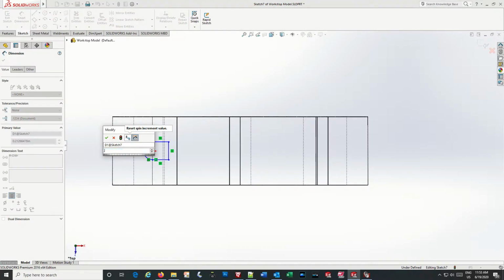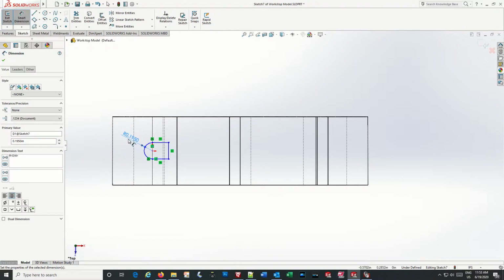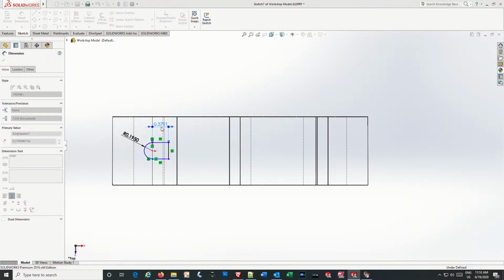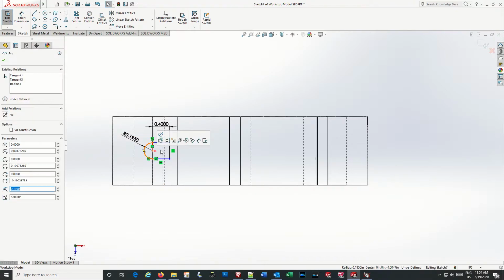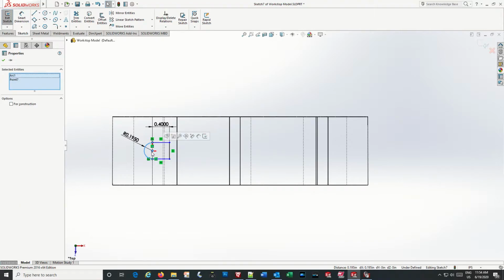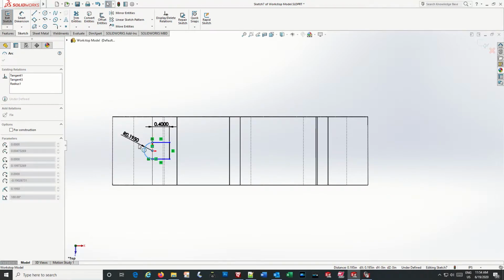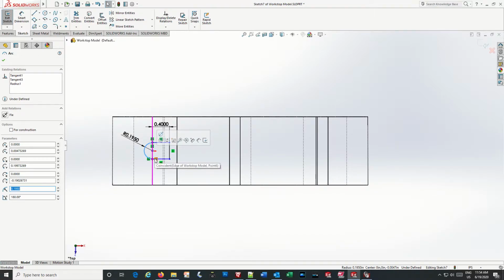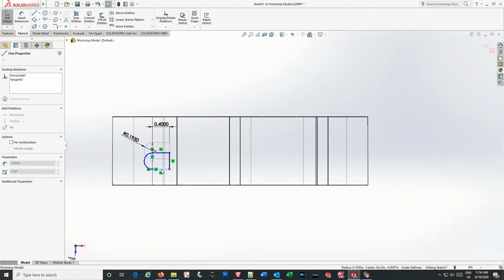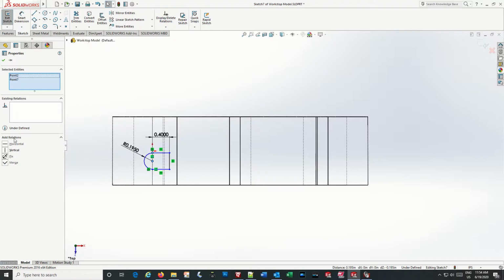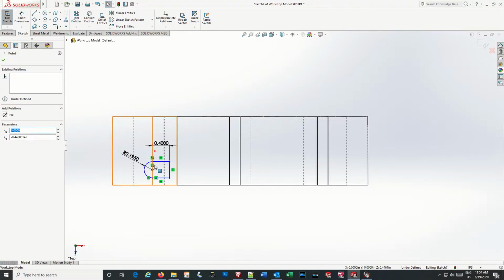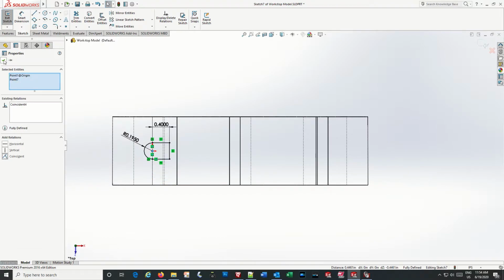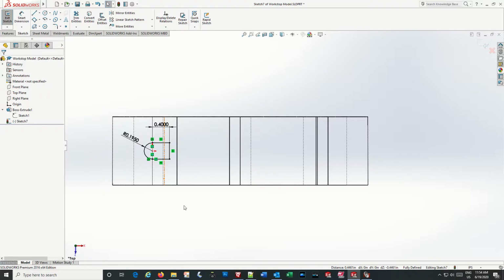This is supposed to be 0.39 divided by 2, that's the radius. And this dimension we can make any, I think probably 0.4 is enough. And let's get the center of this arc locked onto our origin. Maybe it already is. No, it's not. So I want to make that and the origin coincident. Or no, I don't like that, it's not what I want. Let's move that down. We want this and the origin coincident. Now we've got our geometry drawn for the bottom.